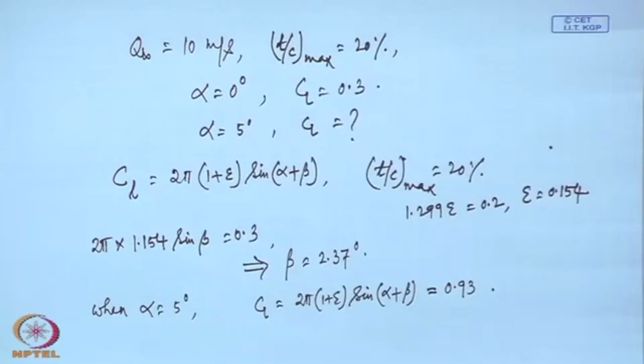Next, you have to find the velocity at the nose of the airfoil. So, once again same procedure, you have to find what is the velocity on the corresponding circle at that point divided by dz d zeta at that point.